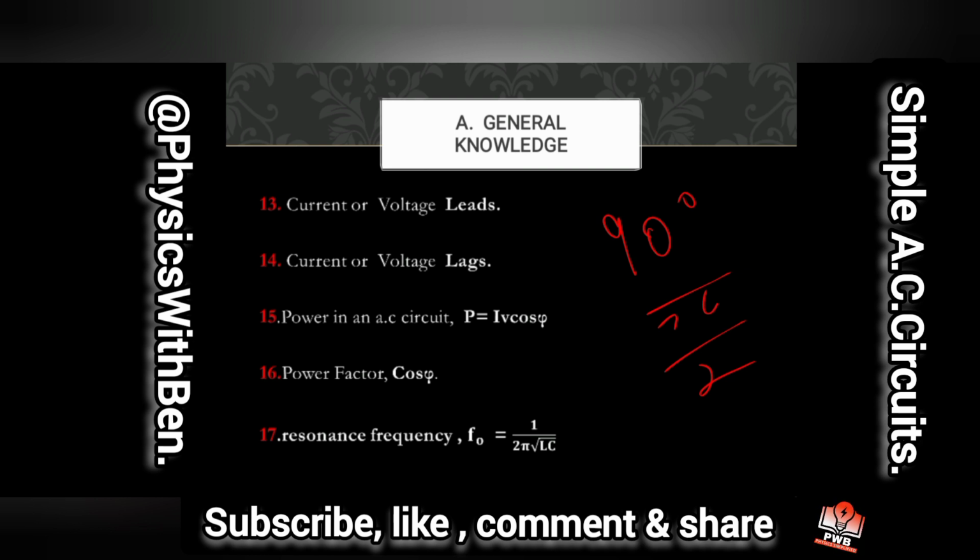So the athlete that arrived 5 minutes later lags the race by 5 minutes. That is just that. They will ask you to calculate the power in the circuit. And the power in the circuit is simply P is equal to IV cos phi, the normal power you know in current, and cos phi is the power factor. So this is the power factor where you make phi the subject of the formula, whatever you find becomes the power factor.